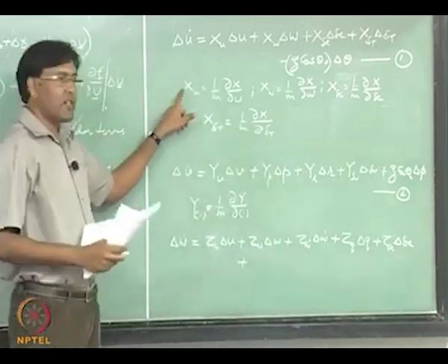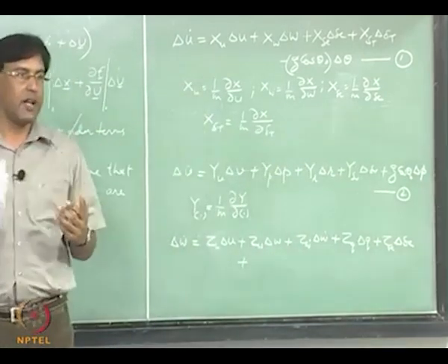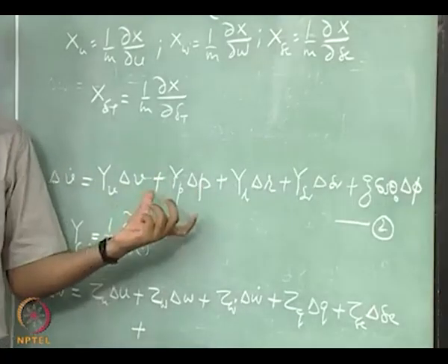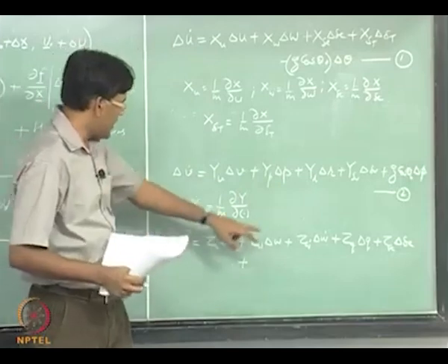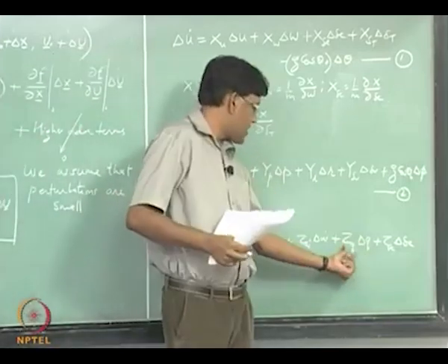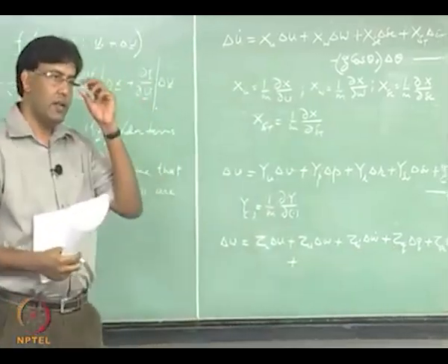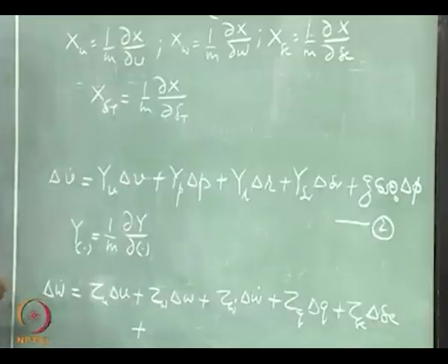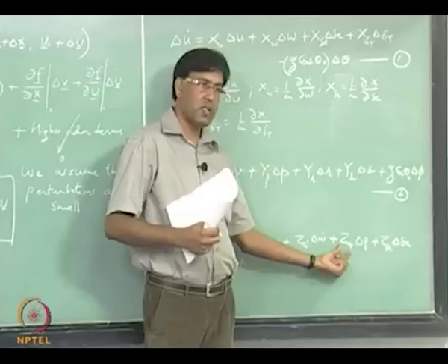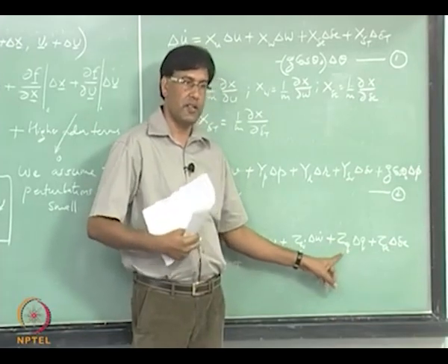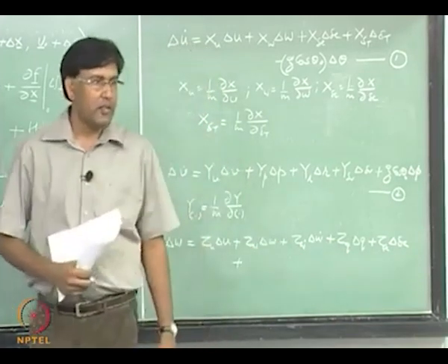In general, these forces are going to be function of all the variables, but we are trying to retain only those derivatives which are important. So, this derivative you see is the change in the force in the normal direction with respect to the pitch rate.